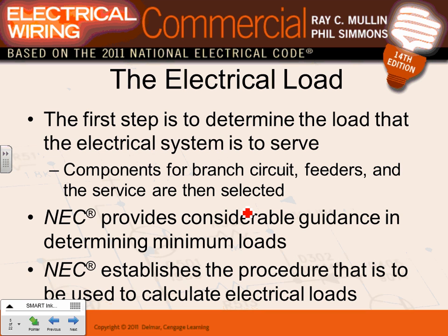So when we do all this, you guys remember how the outcome of this load calculation is really two things, mainly two things: to size the feeders and the branch circuits, right? The outcome of a load calculation every time is to size the feeders and the branch circuits. When we size a feeder, feeders don't sit up in the air. We always land feeders in where? In panels. So you need to land feeders in panels.